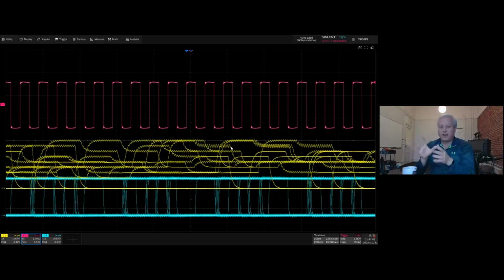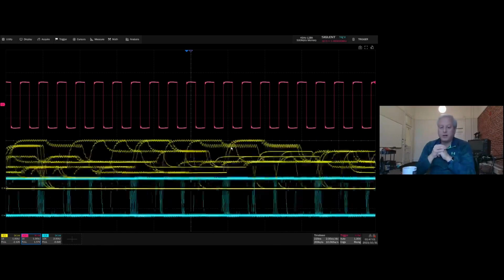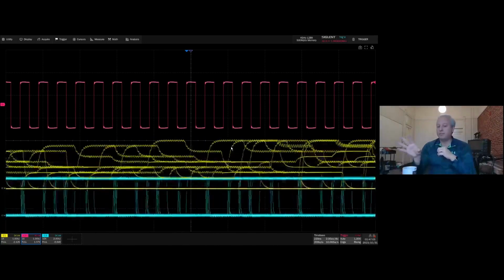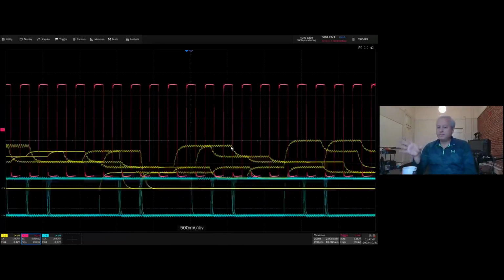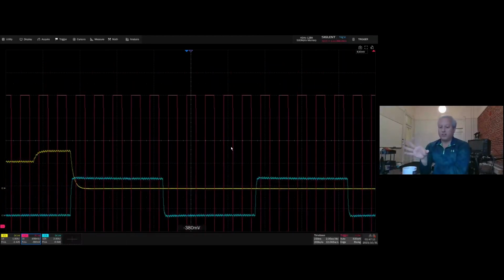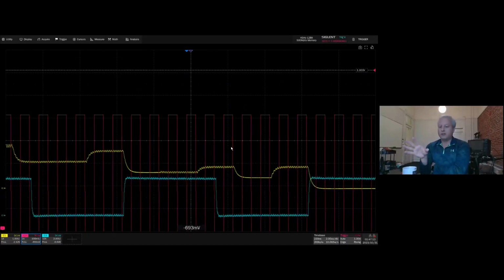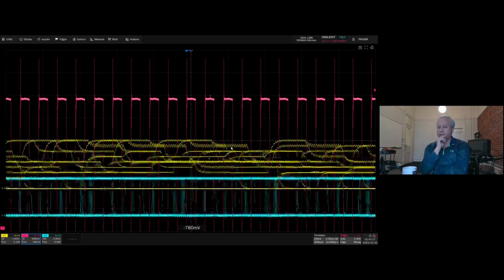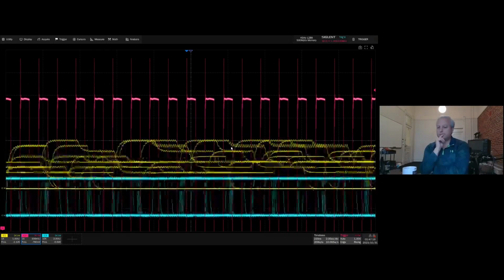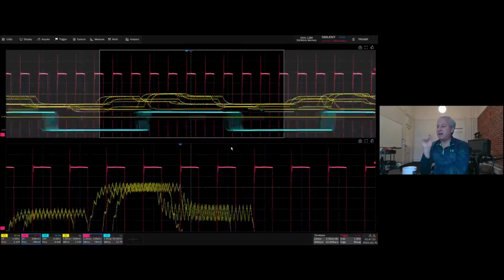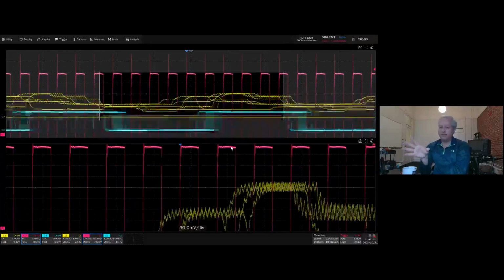So we start by optimizing the range and offset of the pink signal here, so we can trigger on the anomaly. Then, once we get that positioned, we're going to zoom in horizontally and vertically until we have the top of that pulse period spread out. So positioning that, now we're going to start to zoom in horizontally.